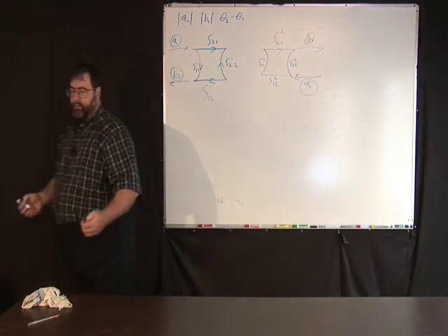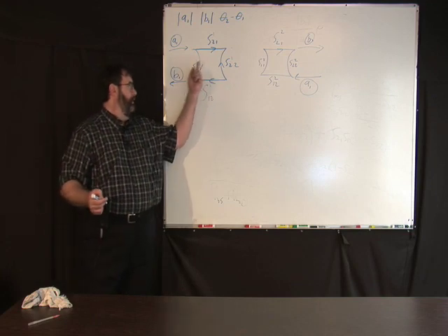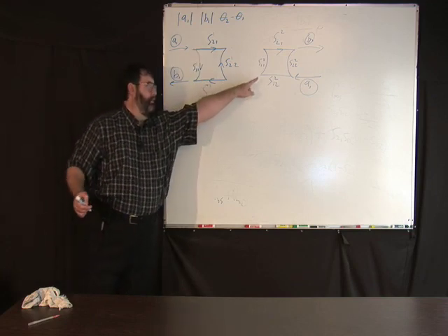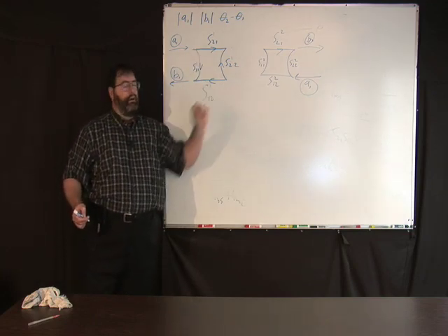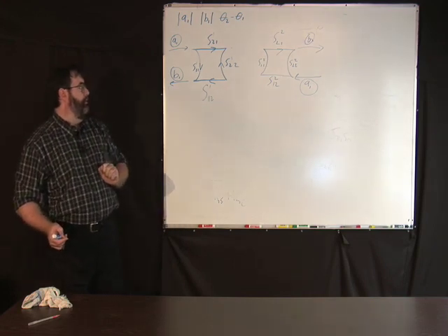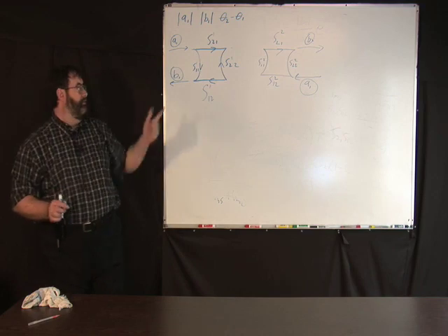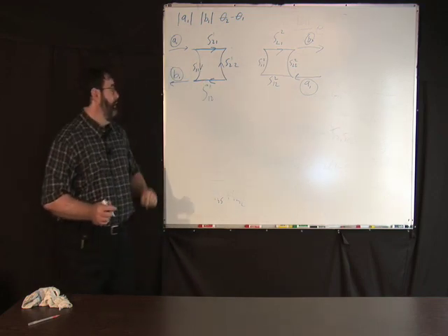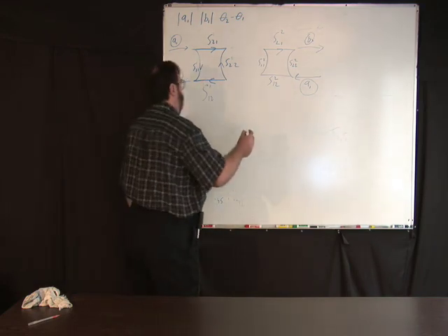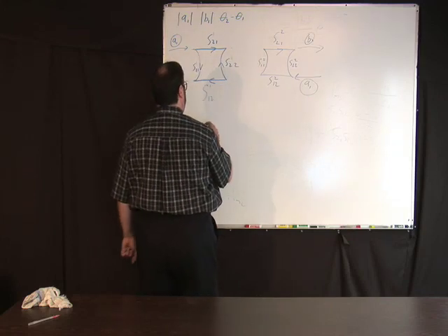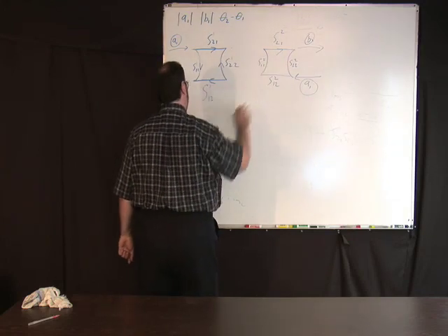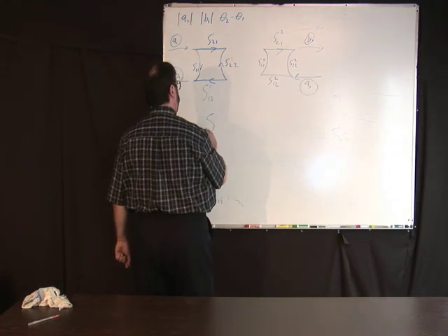Well, we know how to measure these combinations and those combinations, but you have to do one more thing for a network analyzer. You got to do a through connection. When you do that, for this direction, you're going to get a measurement for going through that way from last week.